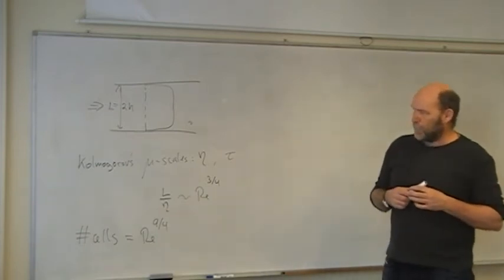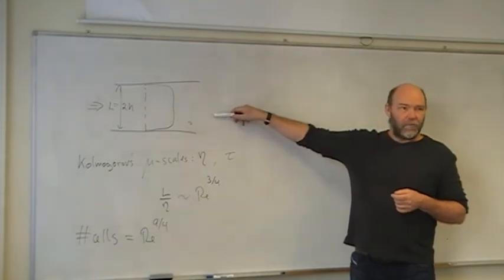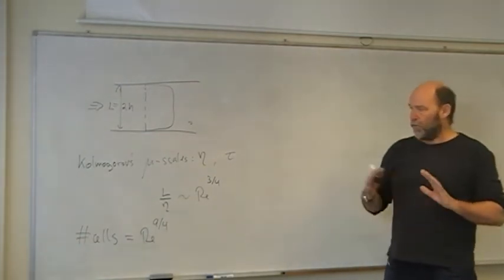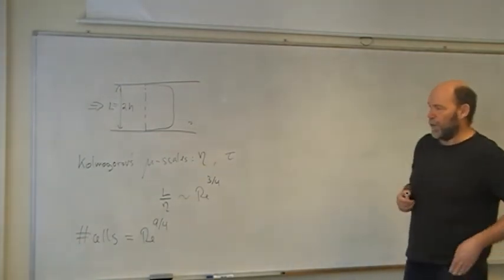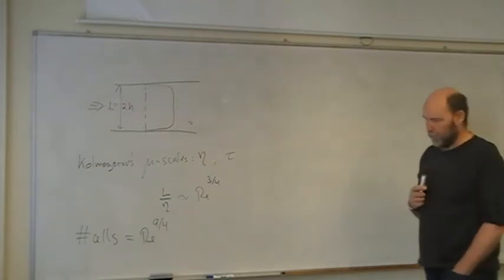So, but that means you have to do 100,000s of time steps for such a simple problem. To get the turbulence correctly developed, organized in space and time. It takes a long, long time. 100,000 time steps, something like that. So the computational demand here is quite substantial.